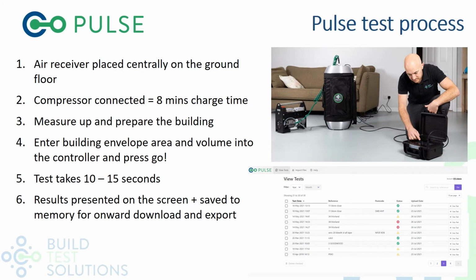Elaborating on the test process a little bit more then, the air receiver is placed centrally on the ground floor. Like I say, all external doors and windows are closed. The compressor is then connected to that air receiver, and the charge time is approximately 8 minutes from zero. Meanwhile, the operative can then go around the building, measure up and prepare for the test, so ensuring all internal